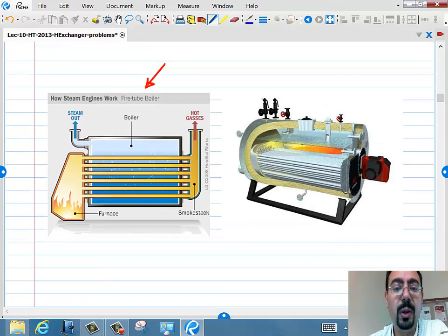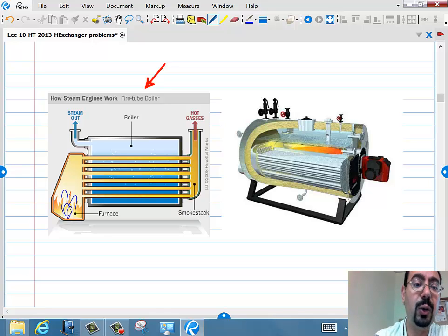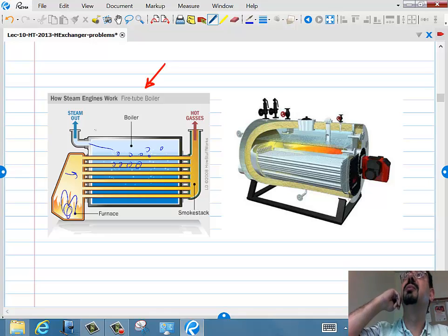And so those are the small boilers that you would find in hotels and hospitals. The furnace over here sends all those hot gases inside the pipe. So the pipe has the very hot gases, while the water is sitting on the outside. It's as if you are making tea in a kettle, right? So the water would boil along the outside, and just make steam. So that's a heat exchanger where one side is completely filled with water and the other side has those hot gases moving in the pipe.